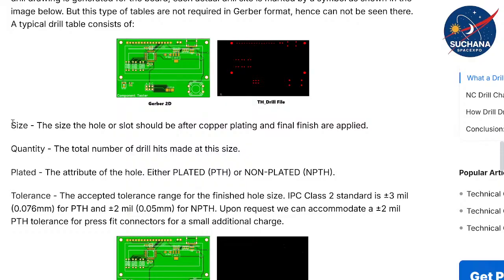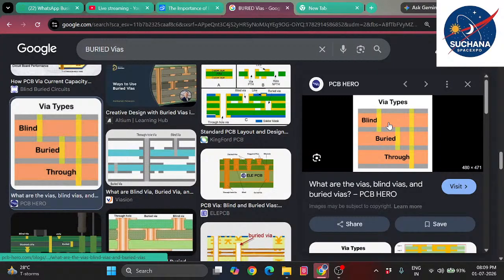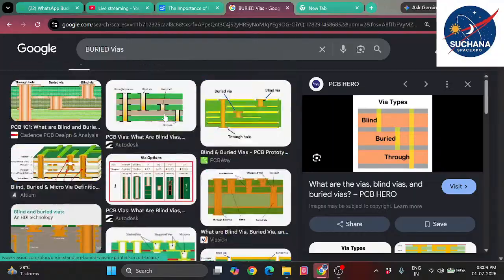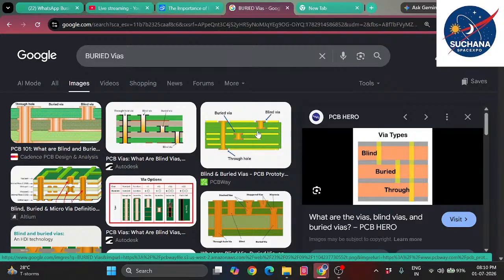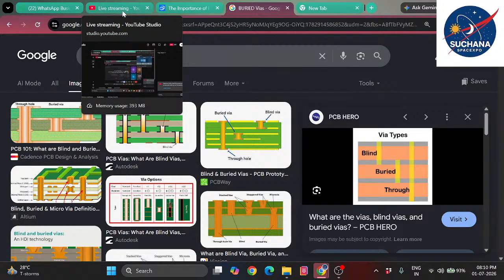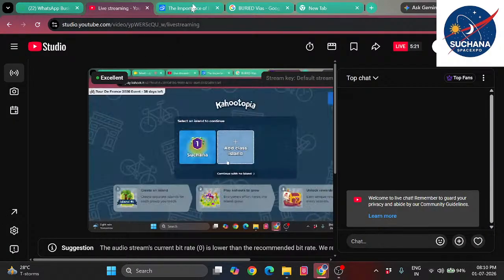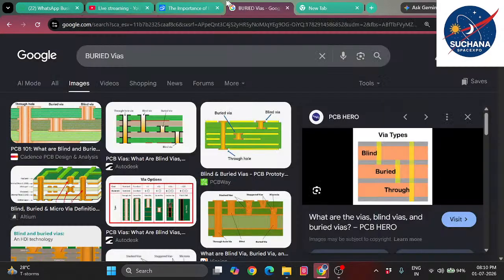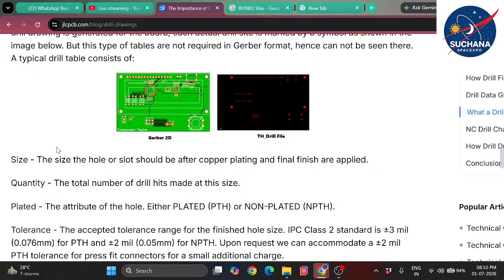The difference between the non-plated through hole via and the plated through hole via is that both are actually the same, but the plated through hole via has an additional lining, a conductive region, which is basically copper. So there would be a radius for the conductive copper lining, and a radius for the hole before placing the copper, which is equivalent to a non-plated through hole via. That means it has two radii. We also need to adjust the thickness of the lining. That's why it has so many parameters.